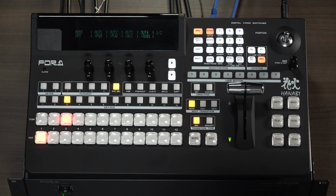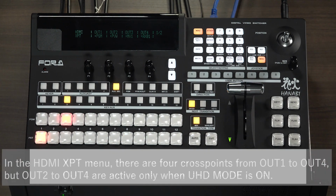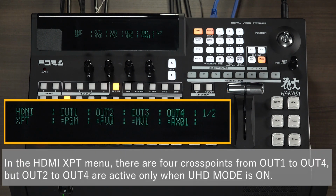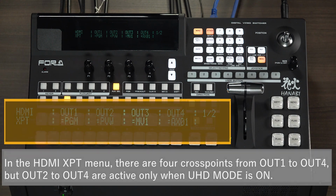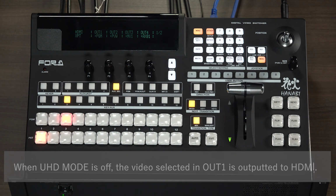The next step is to select the signal to be assigned to HDMI output. HDMI output of HVS-190 supports UHD output. When the UHD output mode is switched on, 4 HD images are combined and output. There are 4 crosspoints, out 1 to 4, in the HDMI crosspoint menu. Out 2 to 4 are enabled when UHD mode is on. When UHD mode is off, the video selected for out 1 is output to HDMI.